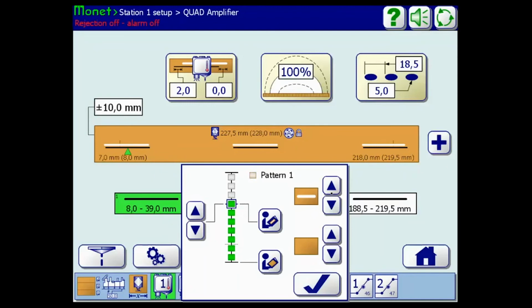So to me, the easiest way is to measure to the top of the sensor. Yeah. That was 65 millimeters, I think. Okay. And that one was it. Yeah, it's the same one. Okay. And then once you set that, you screw the cap on until it's 20 millimeters above the product.